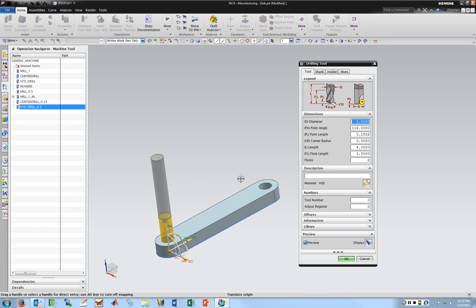If I drill this hole, so if I want this to be a 1/2", more or less, within a thousandth or so, I can't just take a 1/2" drill bit to it. 99 times out of 100, it's going to be a thousandth or two bigger than that, and sometimes even more. Especially if I'm just trying to take this thing in one shot with a 1/2" drill, which I can do. There's nothing wrong with doing that when you're CNC machining, as long as it's nice and sharp. But it's probably not going to be exactly 1/2 inch, or close enough for whatever I'm working with. So I want to come back and use a smaller drill bit. I can actually change the name of this right here.